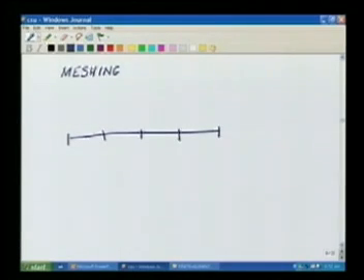How do I define these functions? These functions will be such that, let us take the first node. I will call this function phi1, which is linear in the element omega 1, and it has a value 1 at the node 1 and 0 at all other nodes. So what will that function look like? It will look like this. So I can draw the area under that curve. So this is my function phi 1.